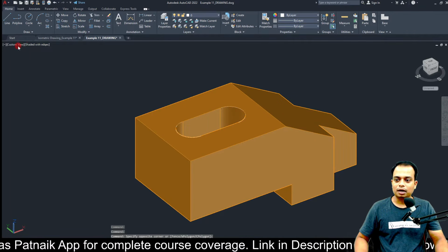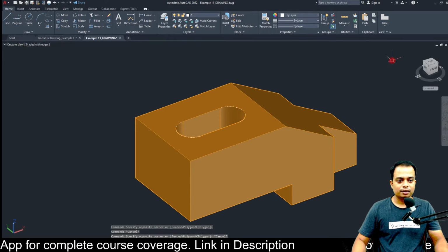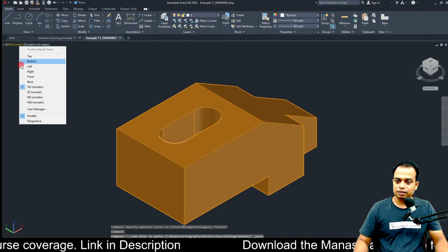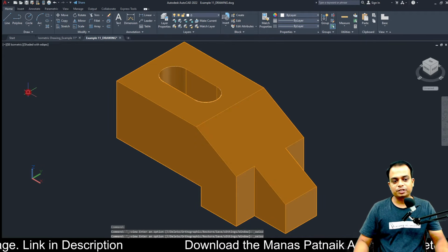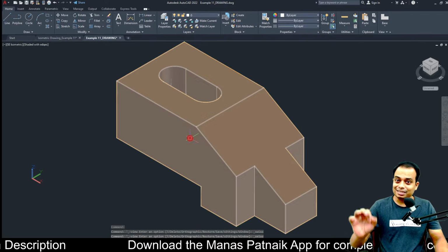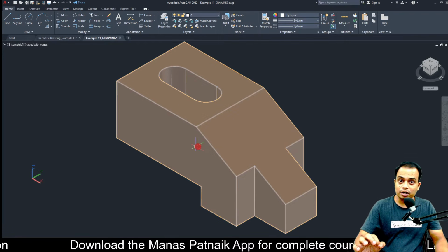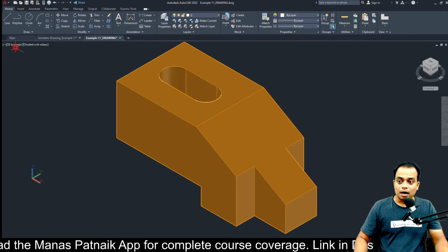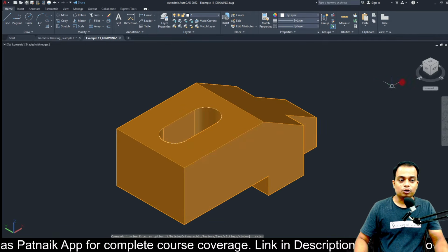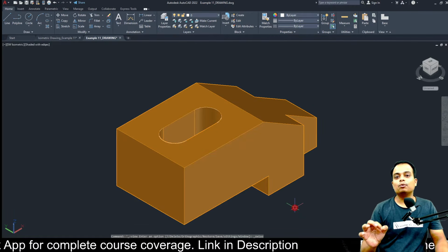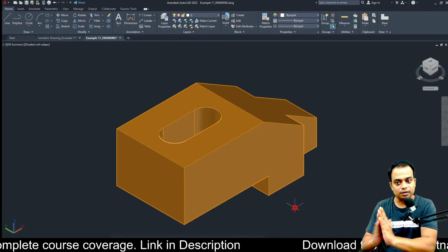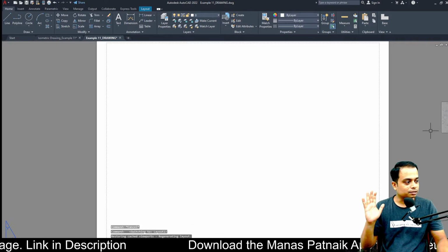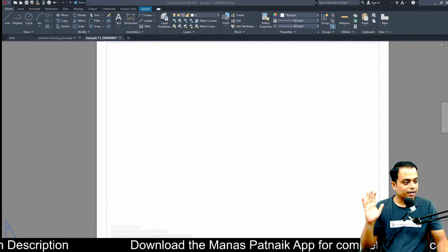Let me just show this to you. This is one way. This is basically southwest isometric. This is one more option of southeast isometric. Whichever way you are drawing this as your isometric view, if you draw this as your isometric view, your front is going to be from over here. You can see this box. However, if you are making this as your isometric view, your front is going to be from over here. So place an arrow once you are done with your isometric view. Done? Okay. One more thing that I would like to bring to your notice is, let me switch off the scrolling text.